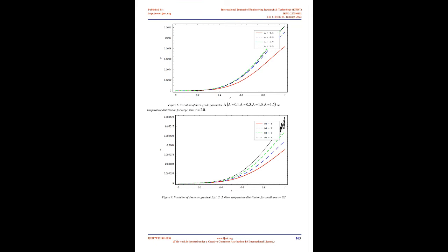Where Tr is the trace of the matrix, the first two coefficients are the material parameters of second-grade fluid, and the first three are the material parameters of third-grade fluid. The constitutive equation for a second-grade fluid can easily be obtained by setting the values of the third-grade material constants equal to 0 in the model given by equation 6. They are called the Rivlin-Ericksen tensors.